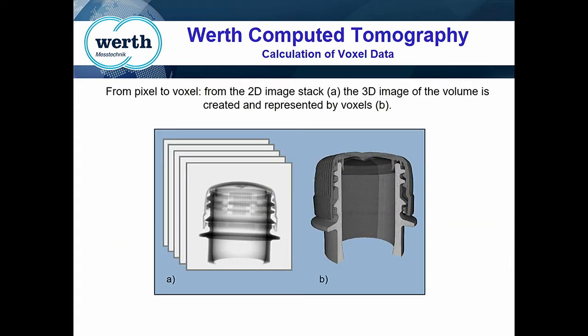And then once you have your stack of 2D images, we compress them into your 3D voxel volume. The color of your part is determined based on density. So totally black would be air. It has no density. And as you can see from this image, the bottle plastic is more dense than the cap plastic.